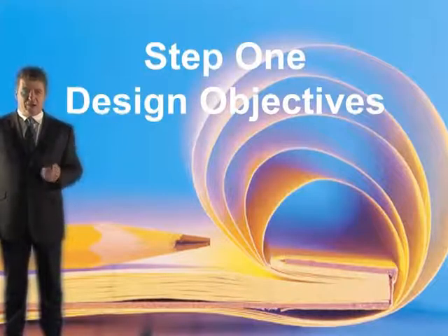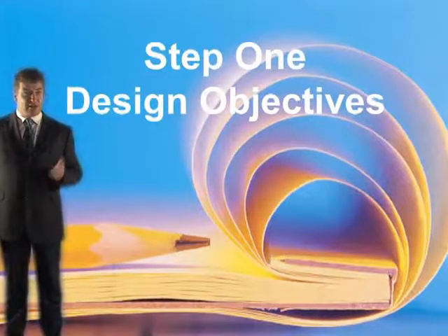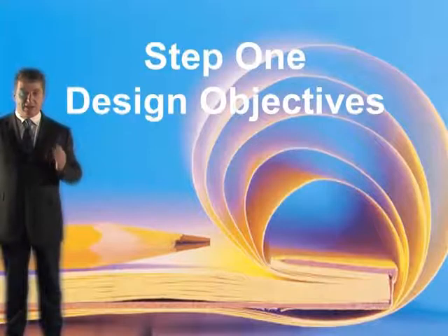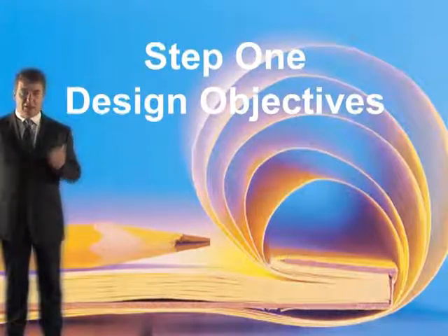Now let's look at the second part, which is basically use the 11-step guide to determine the requirements of the atrium. Let's look at step 1, the design objectives. Well, these are specified as life safety. In other words, to maintain the clear layer height 0.5 metres above the highest opening. And this is for life safety, and also, it will have an impact on property protection. You've also got to ensure that the smoke temperature is not excessively high as to break the glass. So they're the design objectives.